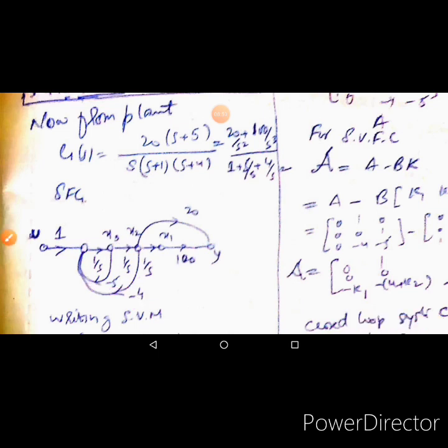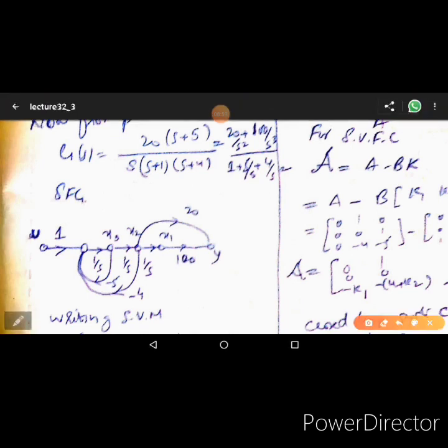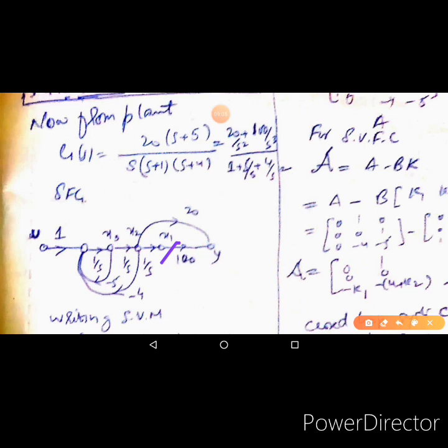In this way we make the signal flow graph, a simulation diagram in the form of a signal flow graph. Now what we do next is that we assign a state variable name at each node, here, here and here. You can start from this side, say calling it x1, x2, x3, or you can do it this way as well, the way we have done x1, x2 and x3. The output of an integrator is x1, then the input must be x1 derivative. If the output is x2, then the input must be x2 derivative. If the output is x3, then the input should be x3 derivative.